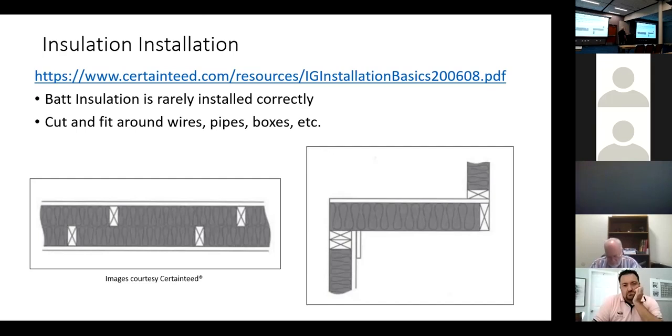We've been testing foam to see. Our concern is you get buried in a wall and can't get to it. If it starts cracking or something like that, the only way you're going to tell is with a camera. I've seen a lot of remodel jobs, and I'm involved in one right now that has some other issues, and it was spray foamed more than 20 years ago. That's good news. The color changed a little bit, it darkened, but I didn't see any cracking. And this was closed cell foam.